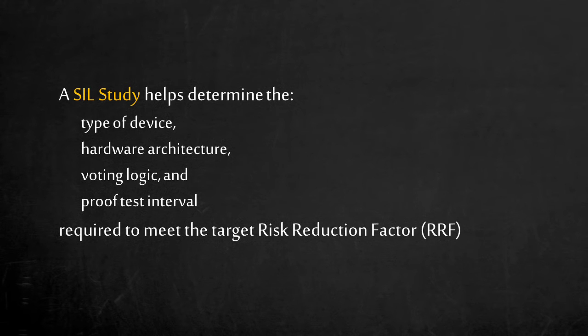Voting logic, how an action is initiated based on conflicting signals, and the proof test interval, how and when each component within the safety function should be tested. All of these are required to meet the target risk reduction factor, or in other words, the safety integrity level of a safety instrumented function.